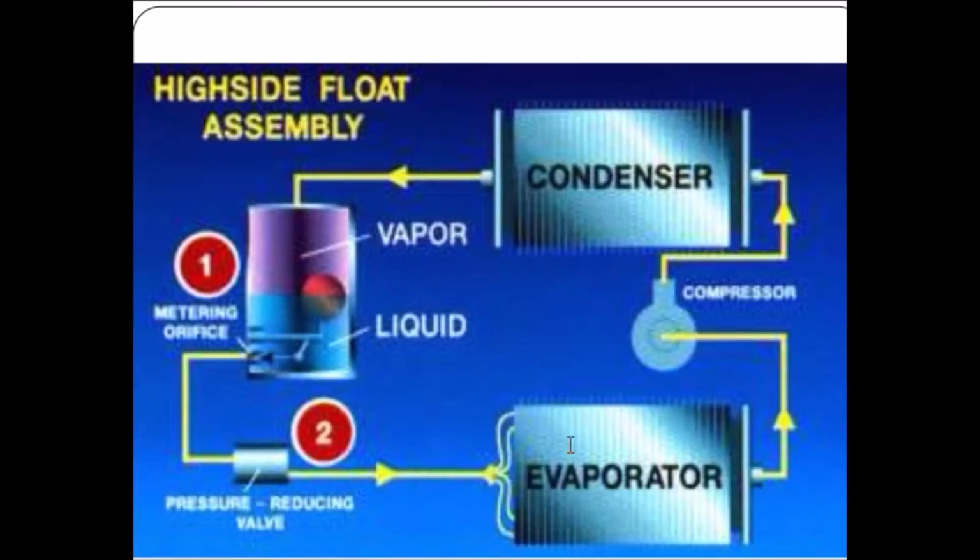Okay, we can check the schematic. Here, this is a schematic of the high side float control. This one is the evaporator, compressor, condenser, and then this one is controlled using the high side float assembly.